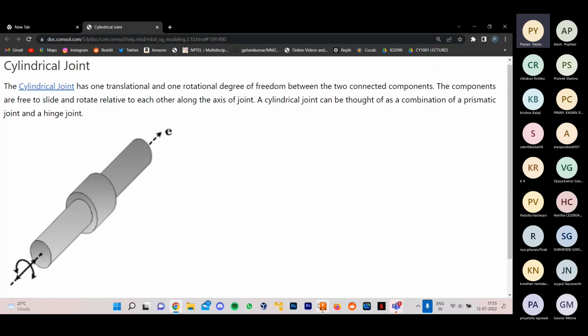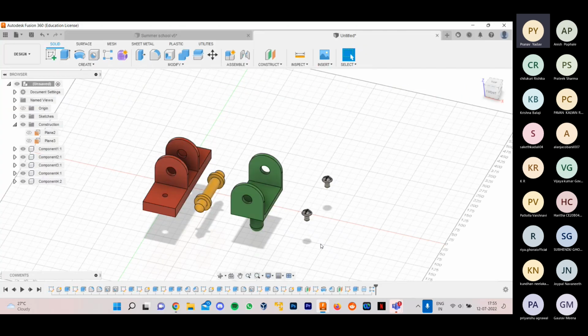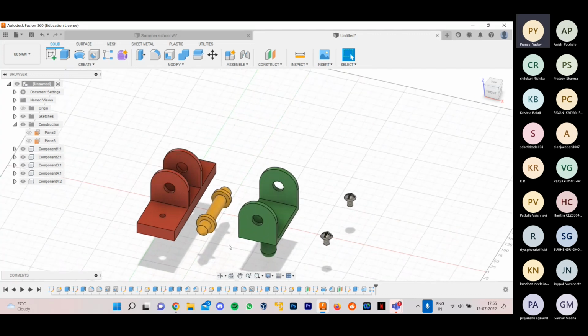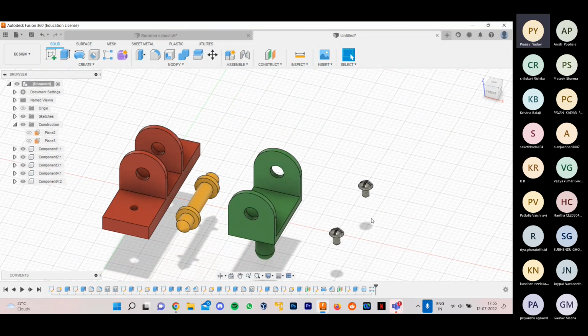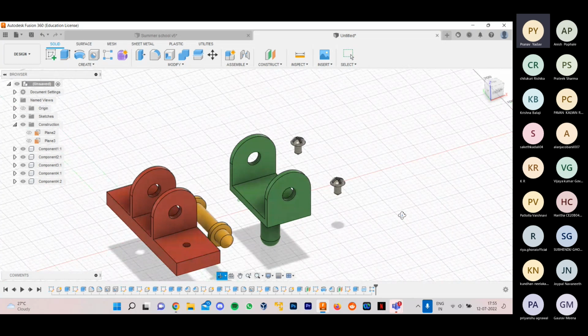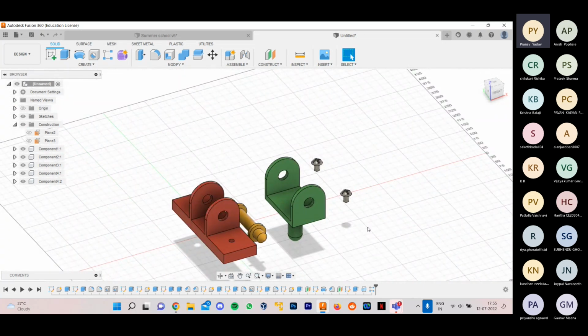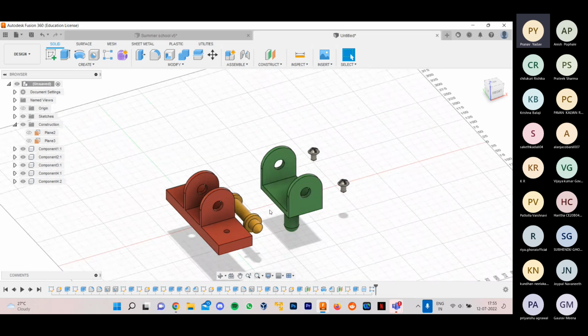It's actually just a rigid joint. So we have to join these components through these different types of joints. You have to guess what these types of joints are. So before joining all these components, let me tell you the most important thing. The first thing you need to do is to ground a component that you should be sure will not move at all.